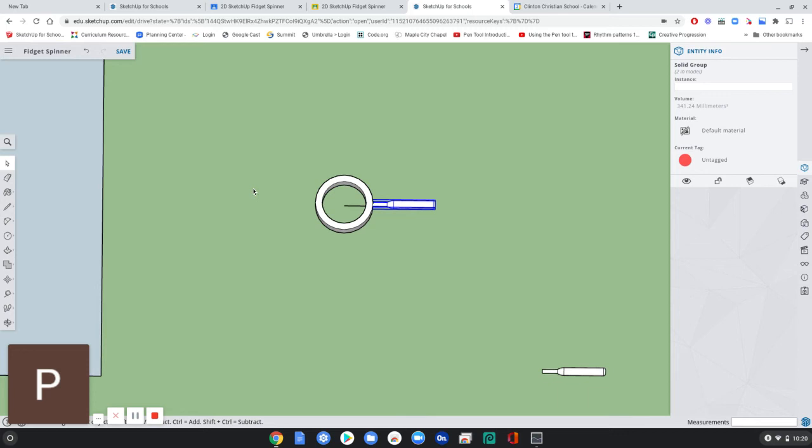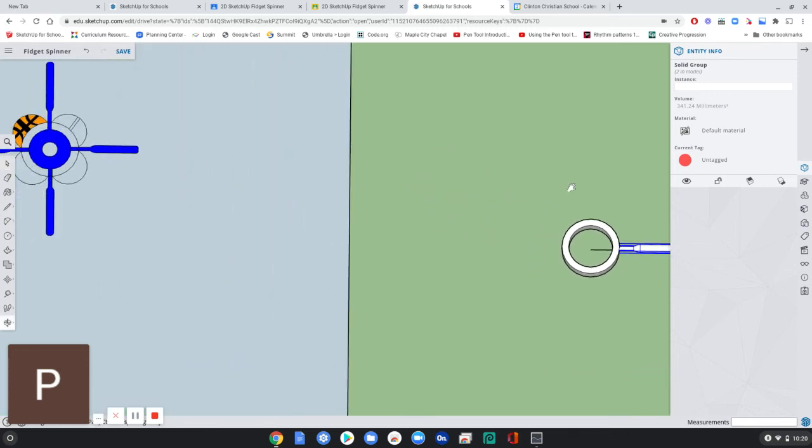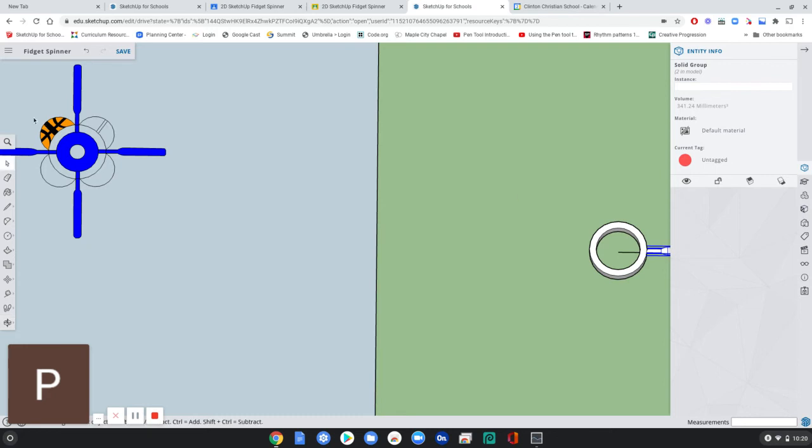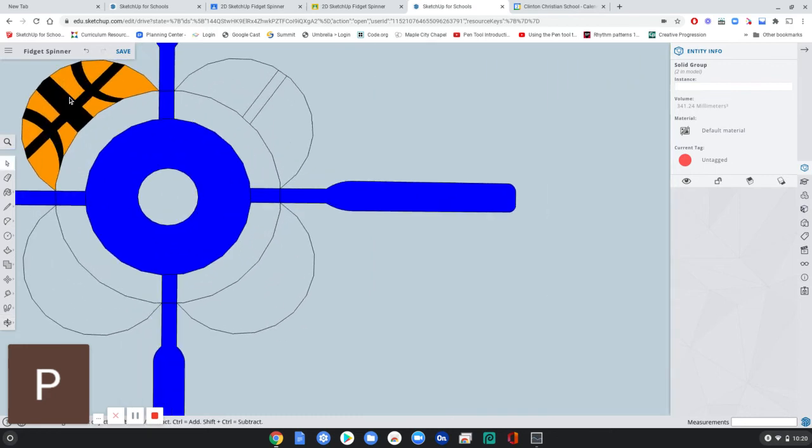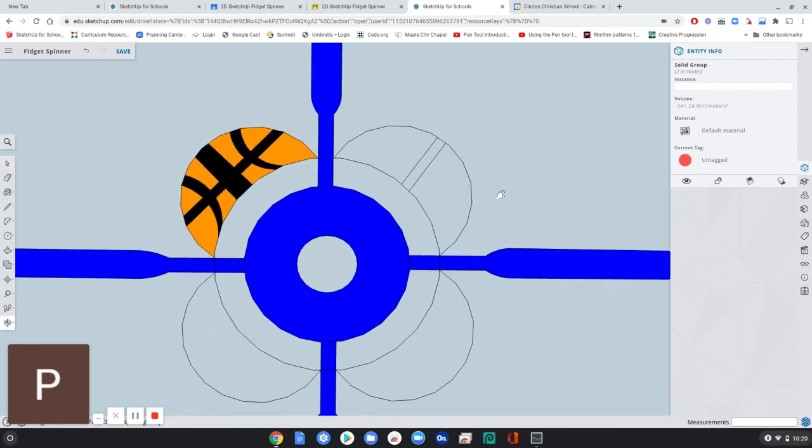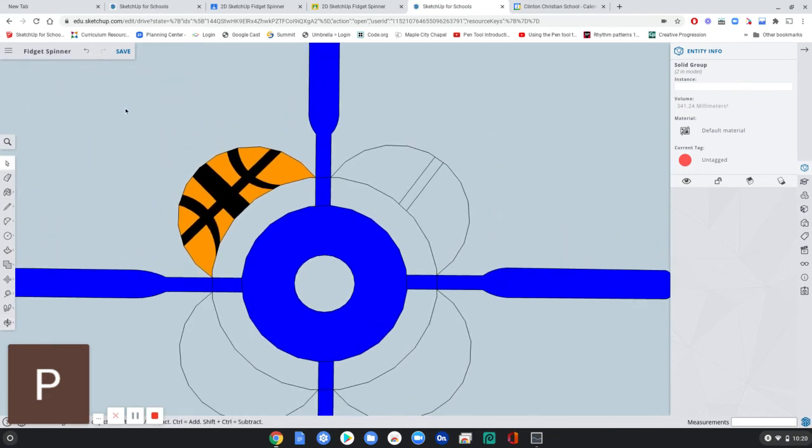So I'm going to use your surfaces and move them over. So let's see, we got a lot of surfaces here. One thing that we haven't talked very much about in class is the different ways that you can select items using a window. So if I draw a window from the upper right to the lower left, that is an intersect window.